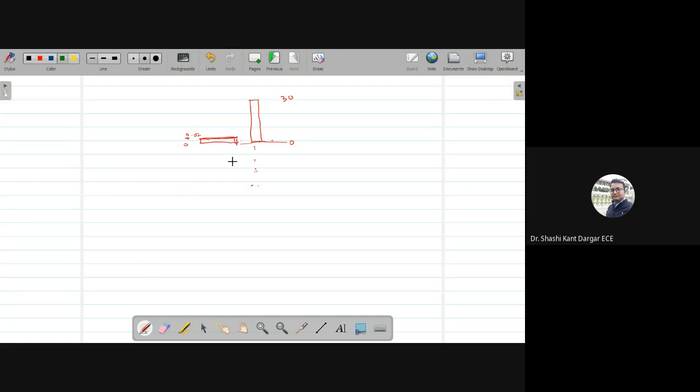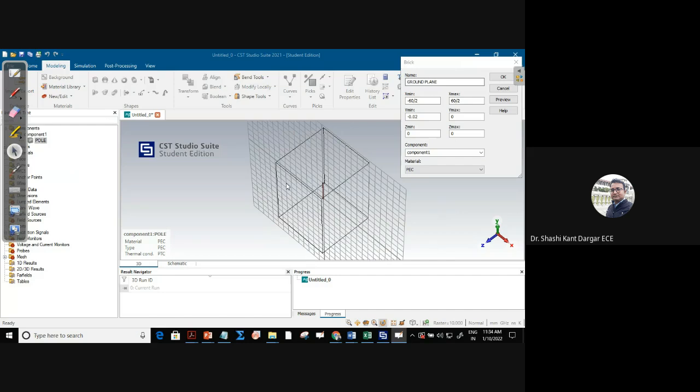Similarly, if I write for the thickness of the plate here that y minimum is 0 but the y maximum is minus of 0.02, the plate creates here, it means just bottom to this. Are you getting my point? Yes? Yes, no? At least respond something, anyone? Yes. Okay, fine. So here we are creating y minimum as minus 0.2. It means it is starting from up, going down maximum to 0. It means I want to overlap this.